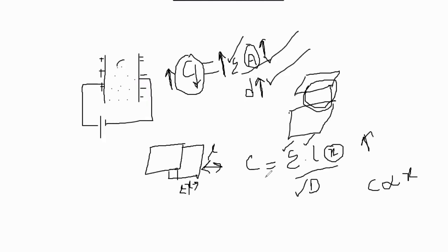In the case of the RTD activity, due to change in temperature, the resistance value changes. So how can we measure it? We have configured it with Wheatstone bridge circuits. So now the bridge will become unbalanced, and accordingly we can measure the output voltage.